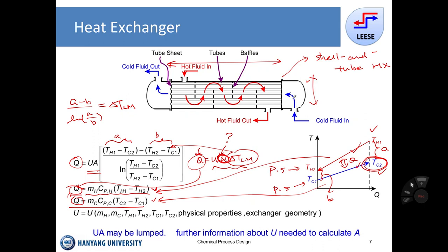One fluid goes through the inside of the tube, and the other fluid goes through the outside of the tube. That is emphasized with this so-called shell arrangement. This horizontal drum allows the movement of the hot fluid. The fluid comes in, then moves up and down along the tube, so heat is exchanged between the cold stream and the hot stream. The hot stream then comes down from this point. This is called the baffle, which creates the up and down movement.